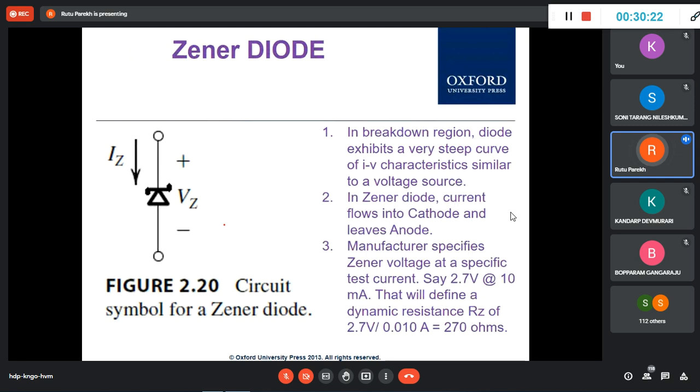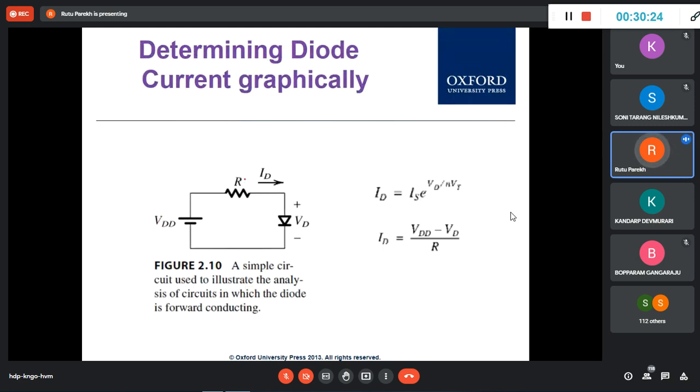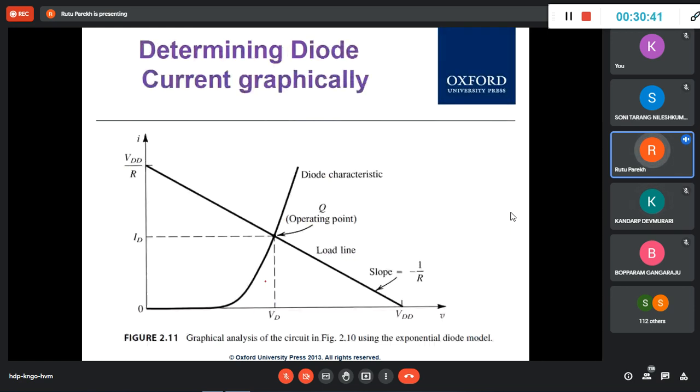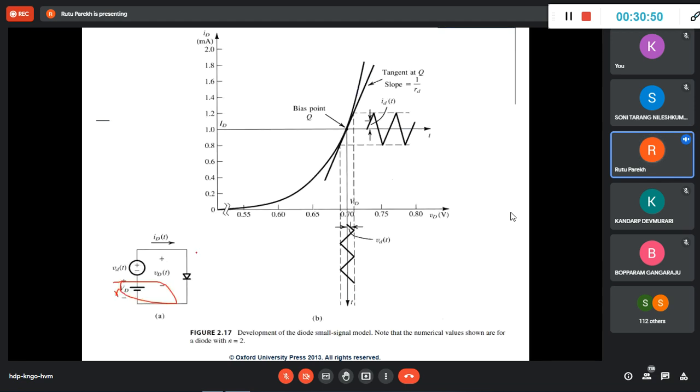It's simple logic only. Anyhow, if you want to use a diode to process your signal, you have to make it conduct. When it is very low volt, you need biasing. And if it is very high volt, you don't need this. Why would you need it? Already it is conducting. So it depends on the application. And the current is changing as per R or as per your changing the VDD. Okay, so this is a simple case of a circuit application of a diode.